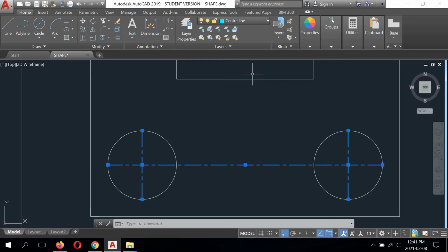All right, so now that we've snapped the edges of these lines to the quadrants of these circles, now we're ready to extend them 6 millimeters. So we're going to select this line here. I'm still not in an active command, right? Type a command here. That means I'm not in a command. So I'm just going to grab the node. I'm going to pull the line in the direction I want to go and type 6. Enter. And that is going to grip that line 6 millimeters outward.